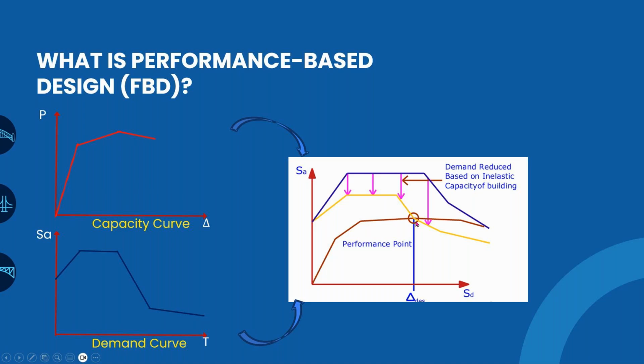So at this particular point, the damping that will occur in the actual event is equated with the actual damping simulated in the structure. That particular point we term the performance point. So we actually need a particular point where the capacity curve and the demand curve meet together.